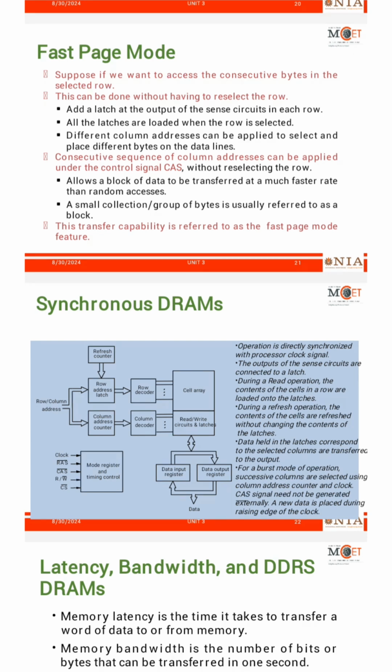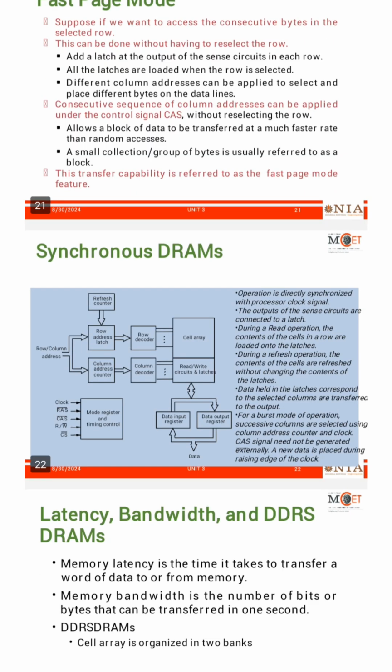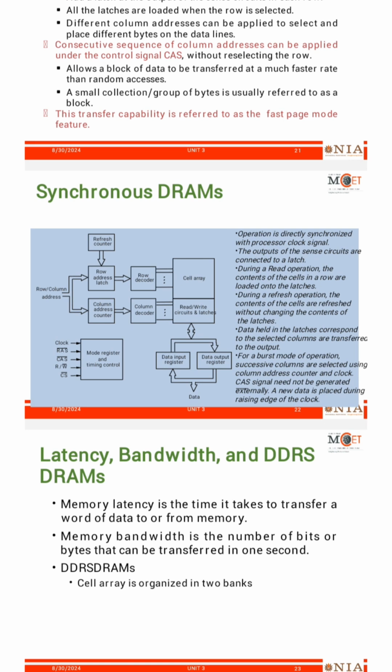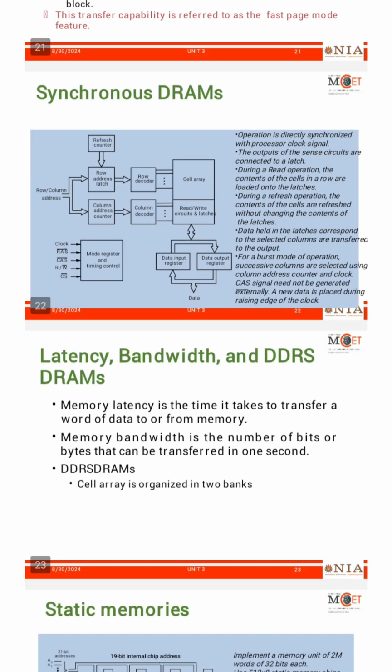Based on the separate clock signals, the output of the DRAM and the data transfer logic can be generated, controlled by the read-write logic and CAS and RAS, where the 21-bit address can be generated from the 32-bit address line. Also, in burst mode of operation, successive clock pulses can be used to generate the specific operations.